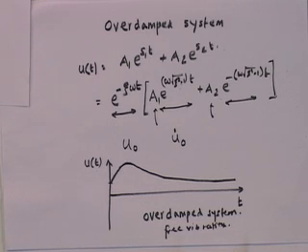No. The free vibration term is actually a misnomer for an overdamped system, because if you give it an initial displacement and initial velocity and it's overdamped, what it will do is it will go like this and slowly come back to this.